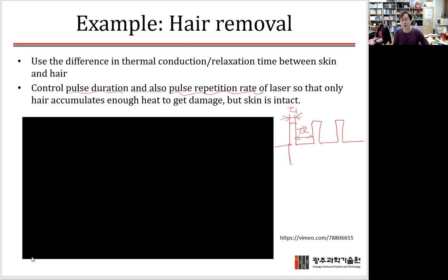So this will be the whole single pulse with the resting time. And then let's say this is the tau 3. So if you divide 1 second by the tau 3, then it will give the hertz, and this will be the pulse repetition frequency.